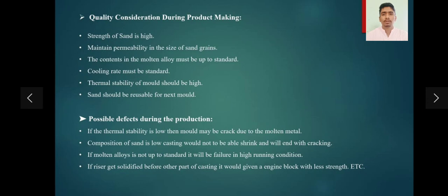If the thermal stability is low, then the mold may crack due to the molten metal. If the composition of sand is low, the casting would not be able to shrink and will end with cracking.